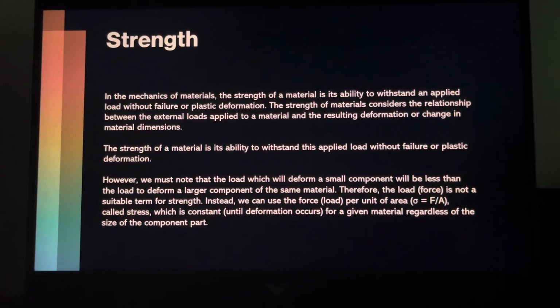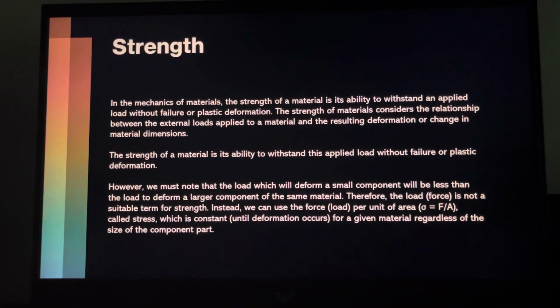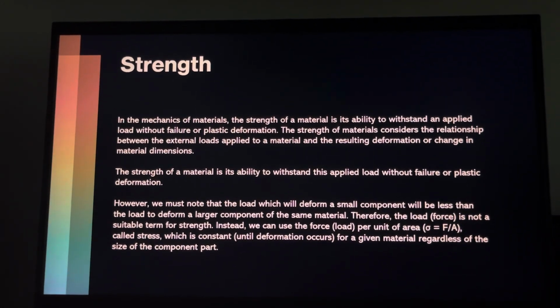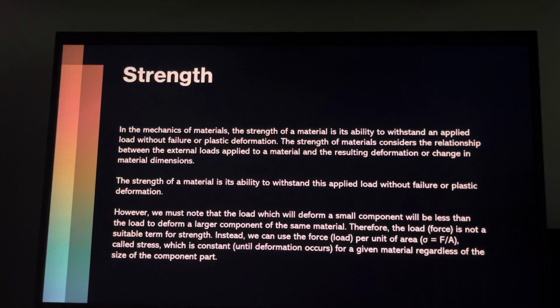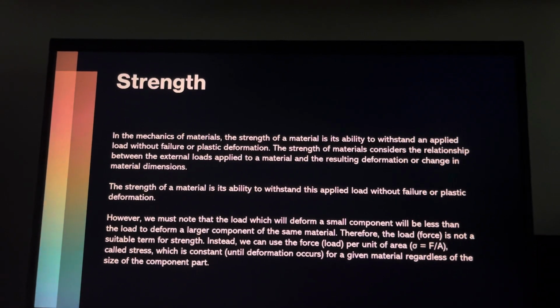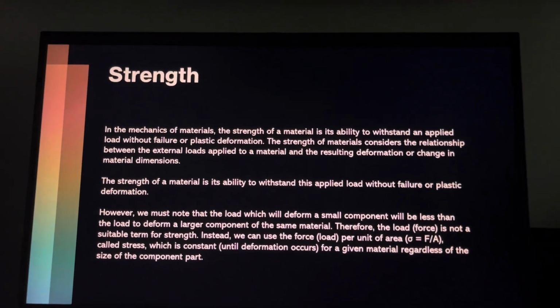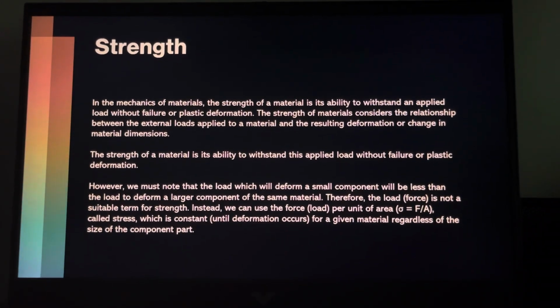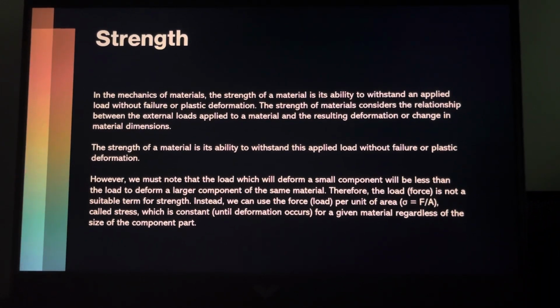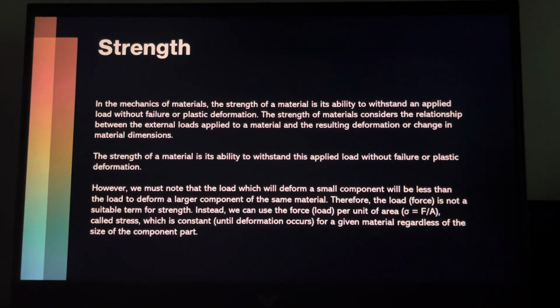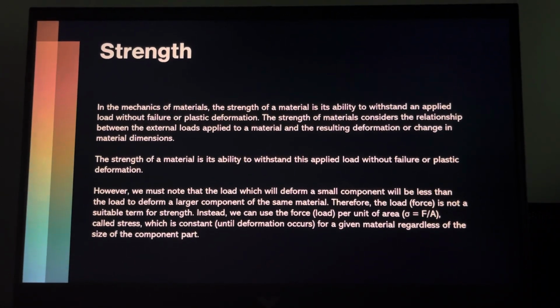So in designing structures and machines, it's important to consider these factors so that the material selected will have adequate strength to resist applied loads or forces and retain its original shape. However, we must note that the load which will deform a small component will be less than the load to deform a larger component of the same material. Therefore, the load is not a suitable term for strength.